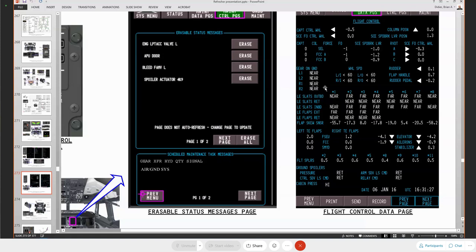And what this signal does, it goes straight through the PSEU to the SCE. Okay, there is no logic from the PSEU applied to that, so it just basically goes straight through. So we're going to use that signal instead of that cable to help control the ground spoiler.